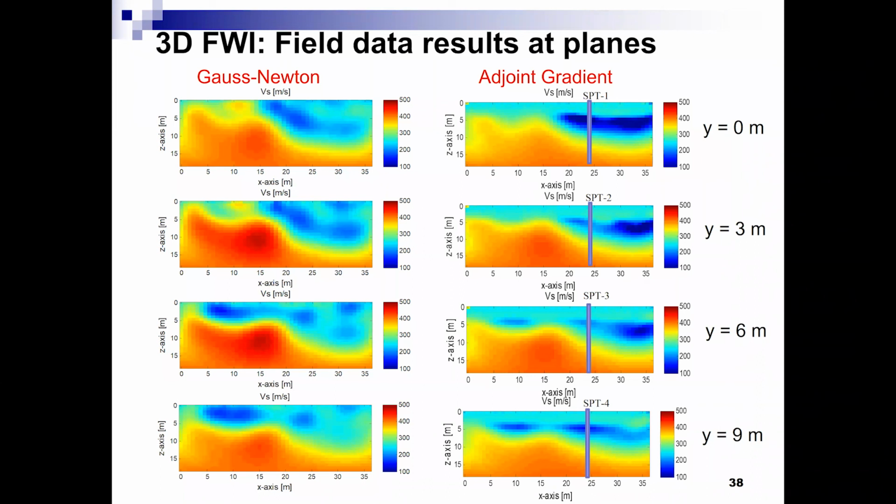We also did 4 different SPT near the chimney at a distance of 24 meters. And here's the result. So that looks like it's pretty consistent, in general, over the whole area. 4 lines, very consistent. So you have shallow rock here and deeper rock here. And here's the SPT.